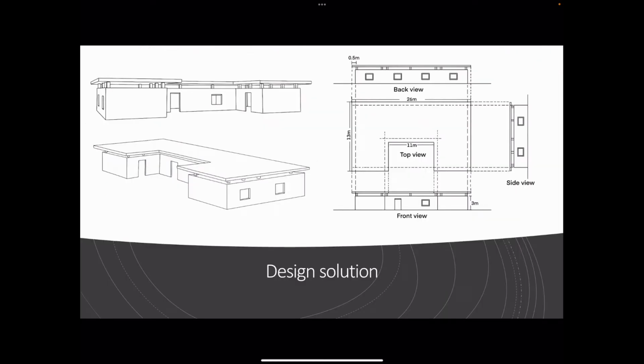These are the three view drawings. The length of this building is 26 meters and the width is 13 meters. The inner structure is made by three rectangles together for three families. You can see the high-raised roof and big eaves. The roof is an area facing sunlight directly, so raising the roof to allow air circulation to carry away high temperature is a good choice. To provide shade in summer and avoid direct sunlight, I designed wide eaves for the buildings.